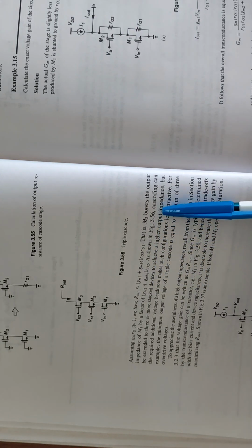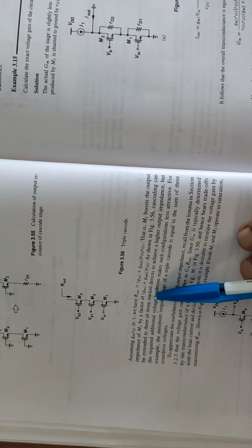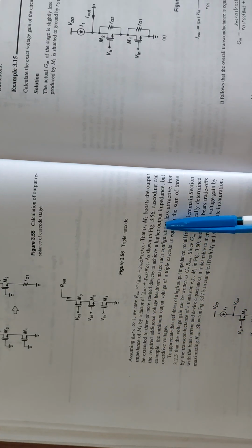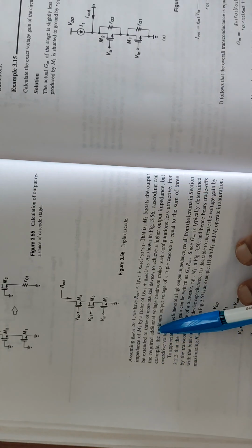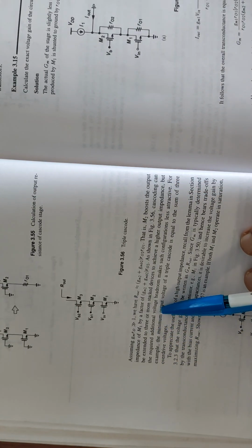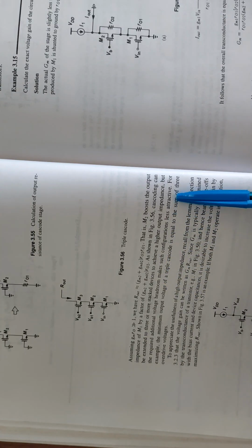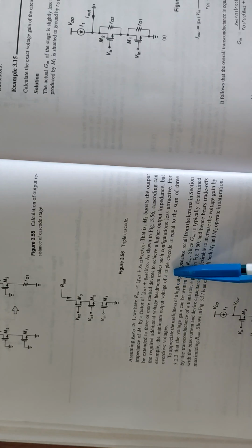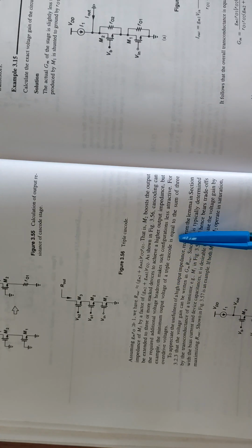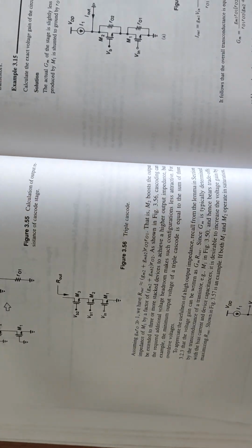As shown in the figure, cascoding can be extended to three or more stacked devices to achieve a higher output impedance, but the required additional voltage headroom makes such a configuration less attractive. For example, the minimum output voltage of a triple cascode is equal to the sum of three overdrive voltages.